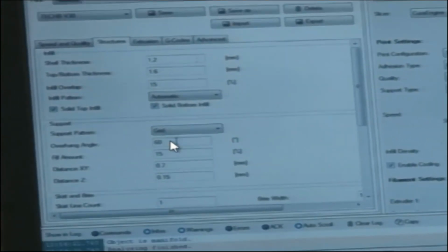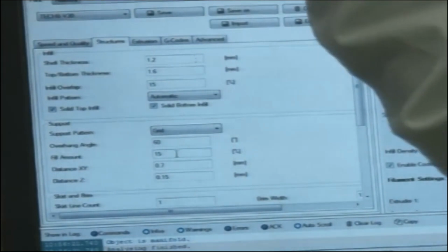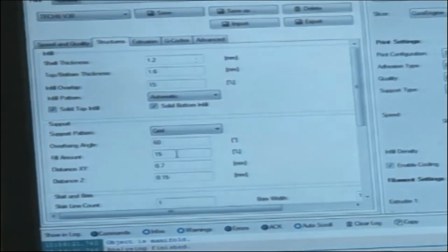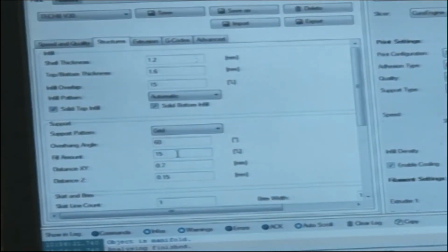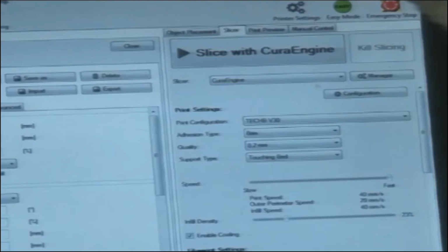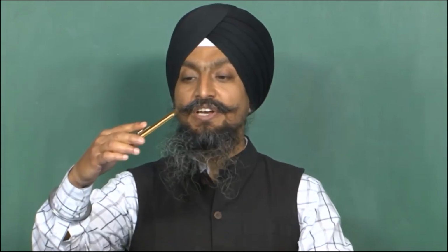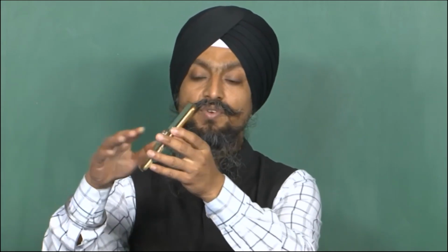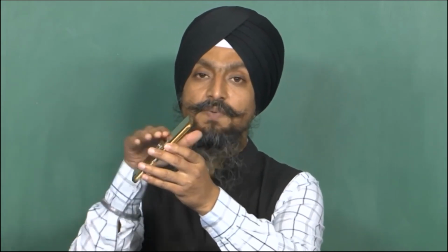The overhang angle is 60 degrees here, for this machinery. If we are going to deposit, or print, or manufacture any job, and it is solid, there is no issue at all. If it is a conical shape, an angle up to 60 degrees is fine; nothing would happen, it just deposits slice by slice.